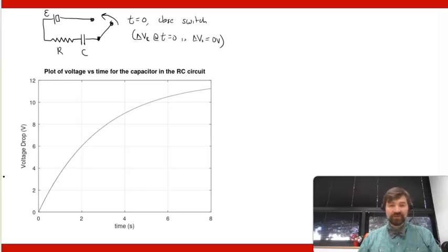As for how I know that it's going to 12, that takes a little bit of discernment when you're not quite at the asymptote point yet. But one way to do it is to understand how half-life and quarter life works for these graphs, or general 1/n lives. So half-life should be the amount of time that it takes to get from 0 to halfway up to whatever you're charging to.